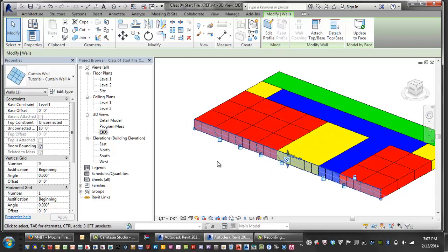Now I want to load in basic mullions, and I'll show you how to do it, it's really simple. You click a button and you put the mullion on each one of these grid lines. So you have this hierarchy developed. But I really don't want to do that. I want to build my own custom panel family.